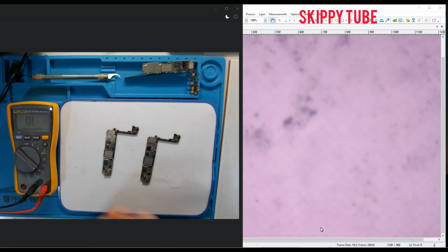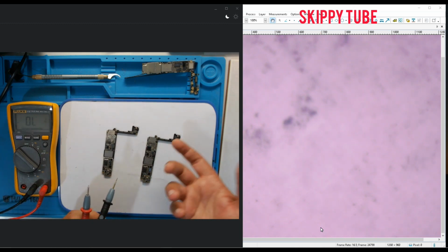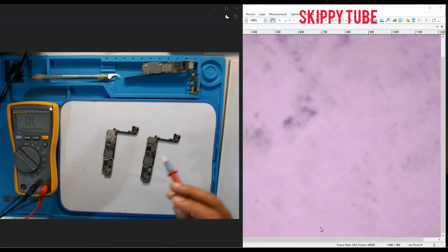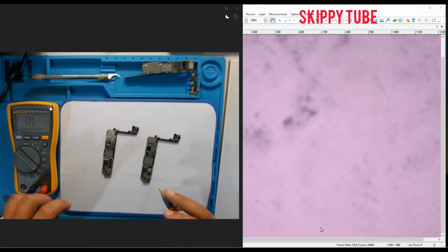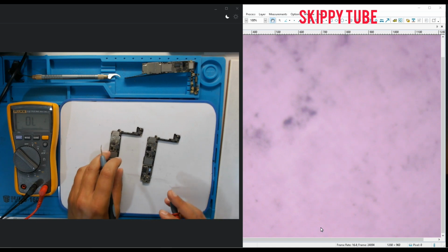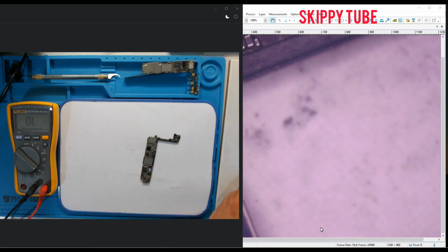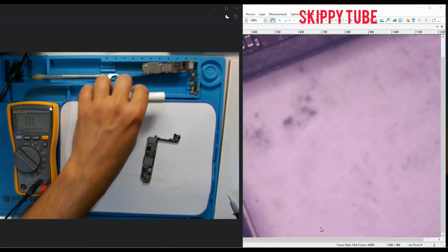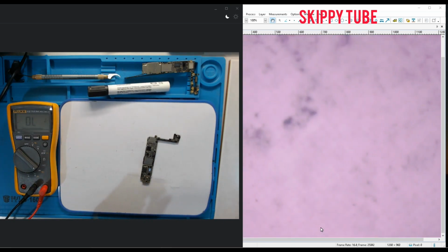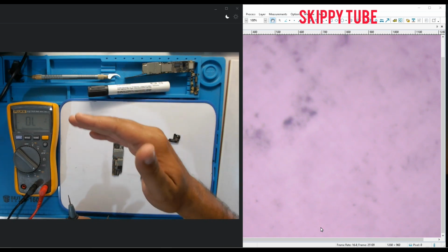I explain about these two names, because you can use the two names. OL has two different meanings: overload and open loop. Right now you can see that this one has a short. I put it in there first, and now we set the DC power supply.